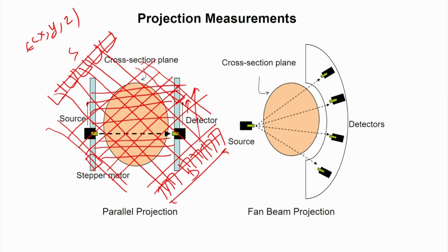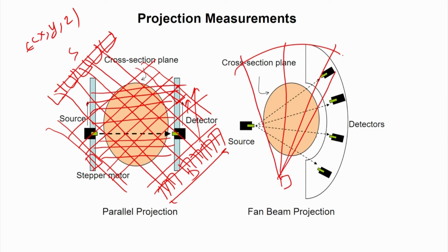Now, again you can move the detector and source, say now the detector and source will come here, and again you will get a fan beam here. Again you can measure the attenuation, then again you can move it, and by doing that you will get the pixel wise information for the same location. Then you can move this carriage upward to a different height and again scan it. So, that is the way this gamma ray tomography works.